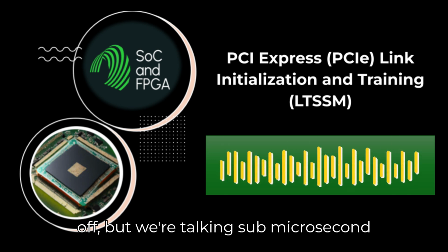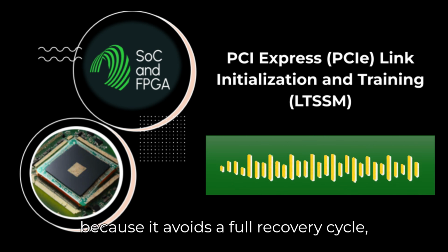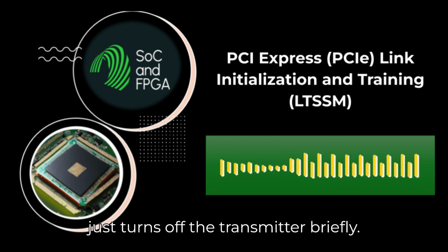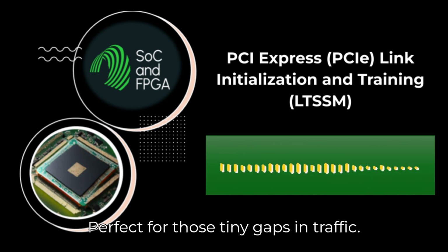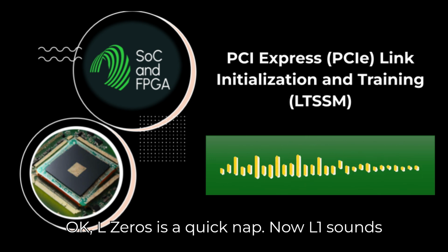It's a trade-off. But we're talking sub-microsecond exit times usually. It's really fast because it avoids a full recovery cycle. Just turns off the transmitter briefly. Perfect for those tiny gaps in traffic. Okay, L0s is a quick nap. Now, L1 sounds like a deeper sleep.